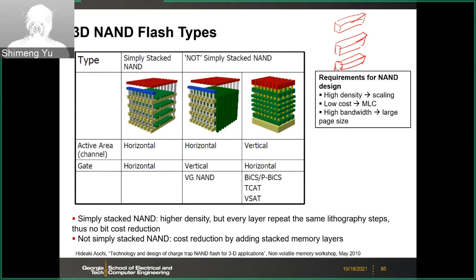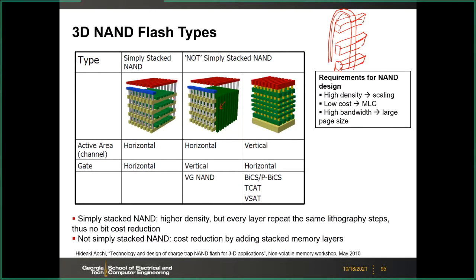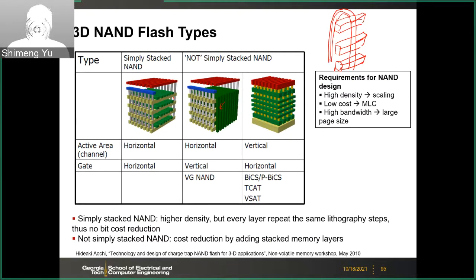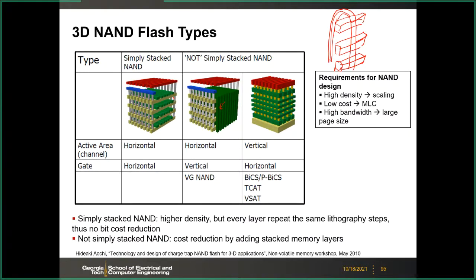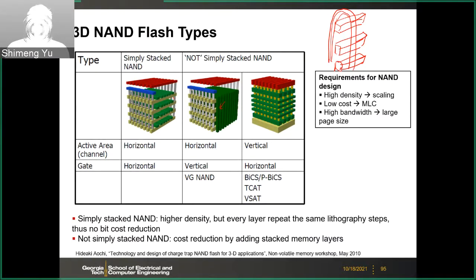And then we have to cover, it's like FinFET, right? We have to cover the fin with the gate. So in this case, these green ones are these vertical gates covering multiple horizontal channels. The good thing about this is to share the gate, because we want to share the fabrication process. That is a key for the 3D stacking.